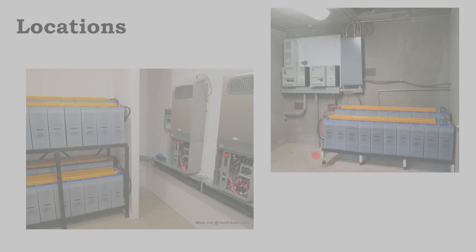But then we also have some other items of concern. The first is the deteriorating agents of these batteries could expose this metal conduit. And you can see this installer didn't care because they're capping their batteries and ventilating the gas out of the building. But you can imagine a local inspector might say, well, that's not good enough. What I want this to be is electrician's gray conduit. Well, then the solar guy might say, oh, but it's a DC circuit, and DC circuits have to be enclosed in metal. And that's why we did an EMT conduit.